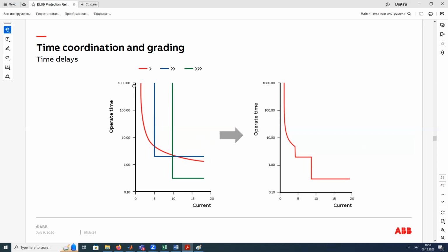Why does this curve exist? Due to the history and the use of fuses. The very simplest and most reliable way to protect from a high current is to use a fuse, because it's a physical element without any moving parts. If the current is higher than the fuse could keep, it's over, and the circuit is disconnected. The fuse construction is a piece of copper wire, and the higher the current, the faster this copper part will be destroyed. So this curve is typical for any fuse.